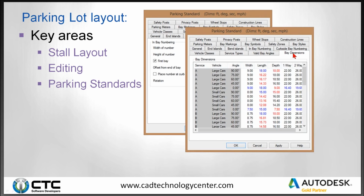So the bay dimensions, and we saw that back in that editing screen. When we pick a parking lot, we're going to pick what size car and what service it is. And the service basically just specifies what width your drive lanes are. So can I get by with 15-foot lanes because I have angle parking? Yeah, because it's going to be a little bit easier to back out. But if I have perpendicular parking, I'm going to need probably 25-foot drive lanes, so I'm able to back out and then make a better curve. So that's your bay dimensions.